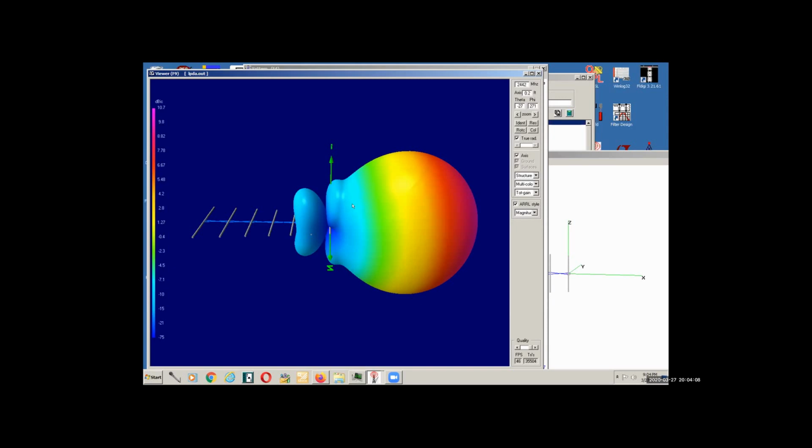So that's actually built into the code. I've built rather complex models with maybe 6 or 8 antennas on a structure like the top of a ship, and used this code to compute the isolation between the antennas. So the answer is yes, you can. It has a built-in routine, and there are really 2 different ways of doing it, but the max coupling is built into the NEC code.